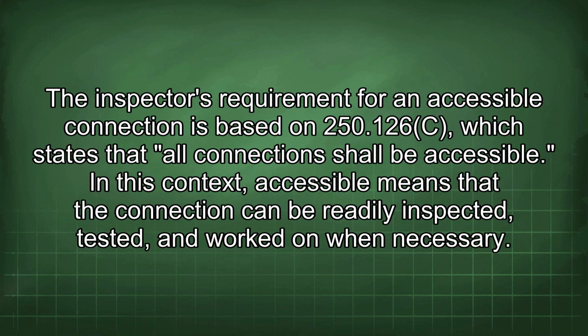connection. The inspector's requirement for an accessible connection is based on 250.126(C), which states that all connections shall be accessible. In this context, accessible means that the connection can be readily inspected, tested, and worked on when necessary.